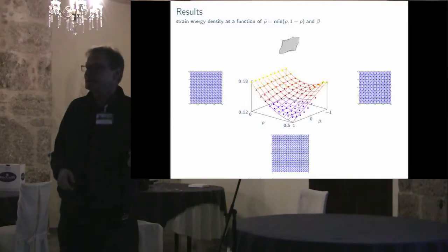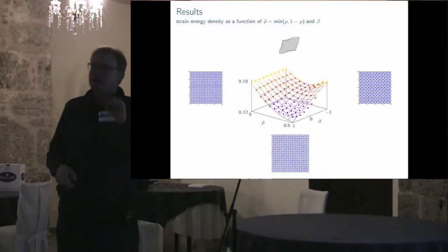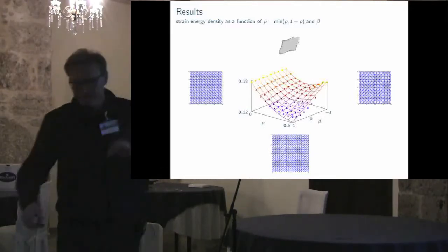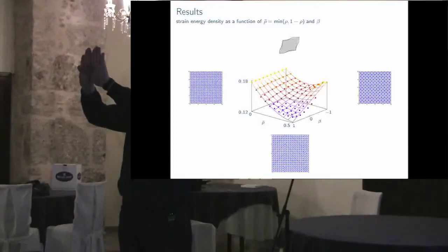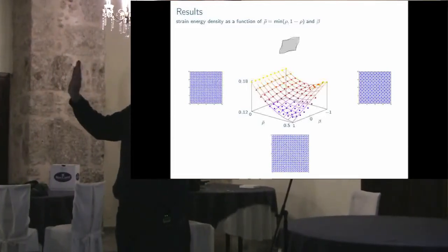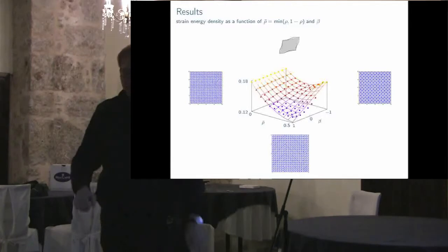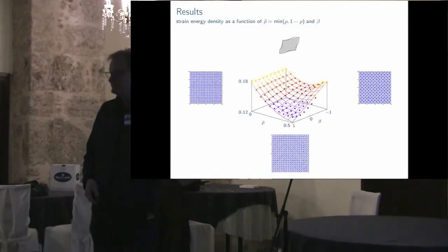Because what I didn't tell you is that for displacement control, high strain energy means high stiffness. So you take this structure, you divide it in two, both parts belong to the strongest configuration, you put them together in the wrong way and you get the weakest configuration you can achieve.